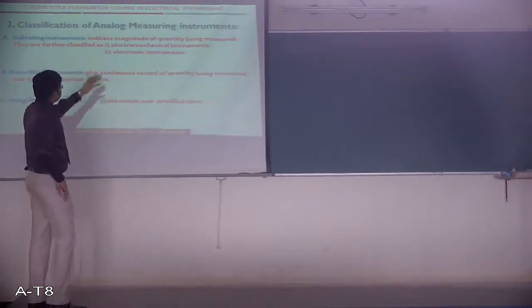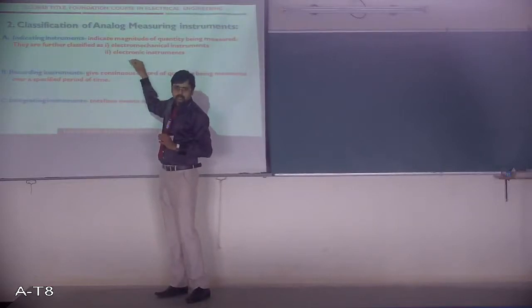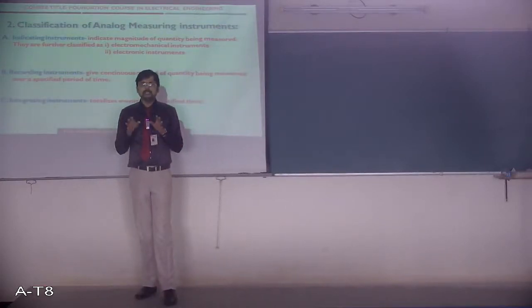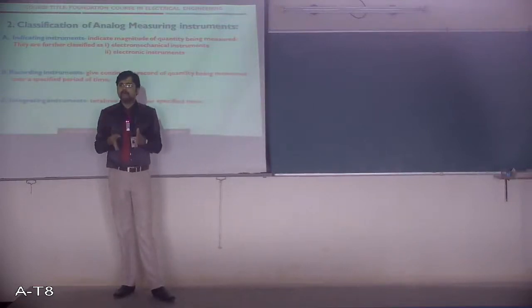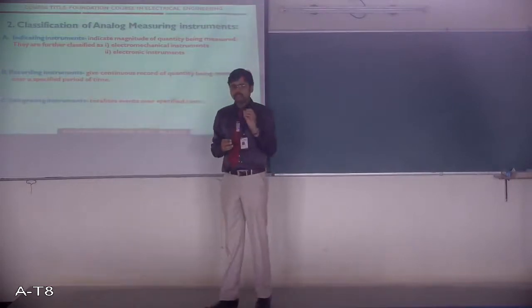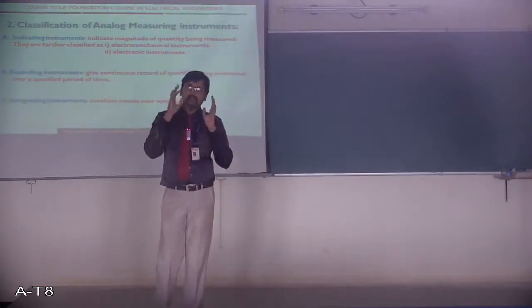Next, you have electronic instruments. Again, this is a category which comes under analog instruments which have some circuit. Instead of the mechanical, rotational system, it is replaced by electronic circuitry which measures the voltage, the current, or the given quantity, and displays it on the board. So your DMM need not be a digital system. Remember, it can have analog ICs and analog circuits inside. So don't be misled by the type of display you see on the instrument. Some are still analog. To identify analog versus discrete, if the reading changes continuously with the change in the input, it is analog.